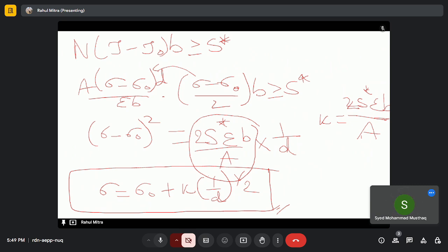Once we reach below like 20 nanometers, the critical size of the grain, then again the yield strength will decrease. See, if I draw that, this is my yield strength and this is my grain size. It will go on increasing, and once I reach a critical size of the grain, this value will again decrease. For some materials this value will be constant, and for some materials this value will decrease.